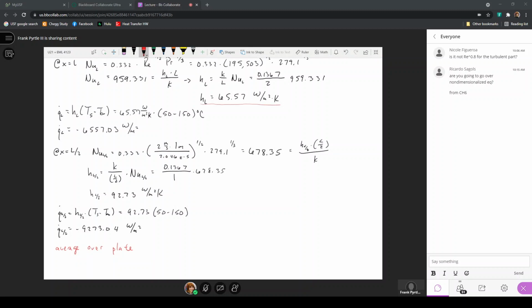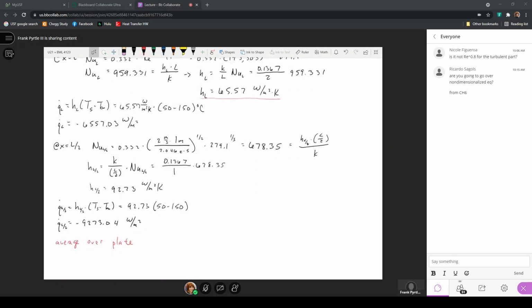So this average value that we calculate, I mean, a good place, since it's a laminar flow condition over the entire length of the plate and it's always decreasing, that means that the average value should be greater than the local value at the trailing edge of the plate. And we'll consider something else when we look at this expression once we made the calculation.